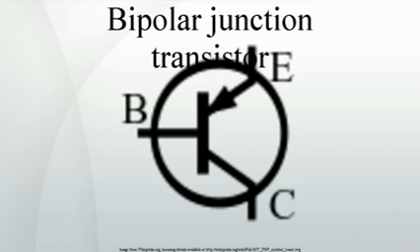Regions of operation. Bipolar transistors have 5 distinct regions of operation, defined by BJT junction biases. The modes of operation can be described in terms of the applied voltages. This description applies to NPN transistors. Polarities are reversed for PNP transistors. Forward active: base higher than emitter, collector higher than base. In this mode the collector current is proportional to base current. Saturation: base higher than emitter, but collector is not higher than base. Cutoff: base lower than emitter, but collector is higher than base.